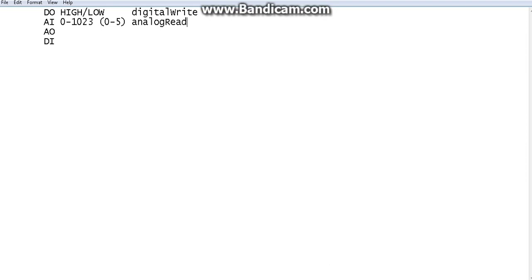Using the keyword we take the input. And then when it comes to analog output, we are giving analog output values from 0 to 255, or in other words from 0 to 5 voltages, and the keyword for this is called analog write.